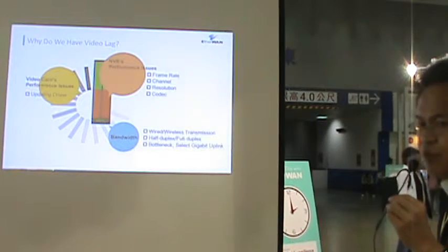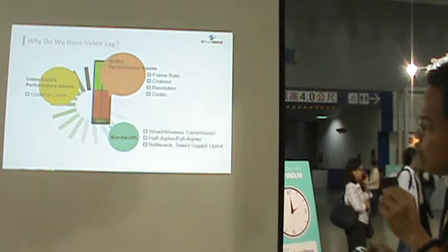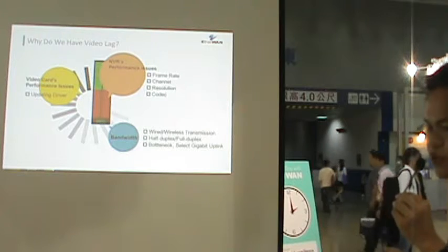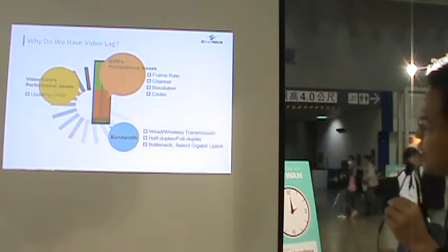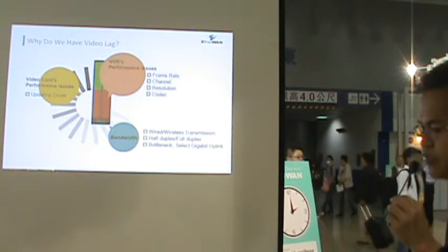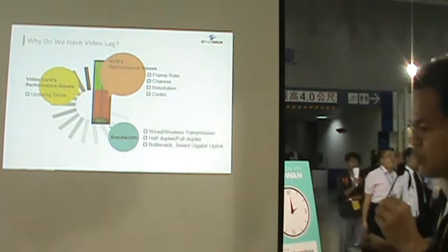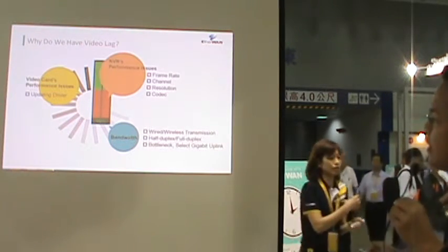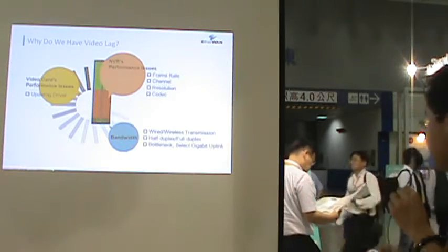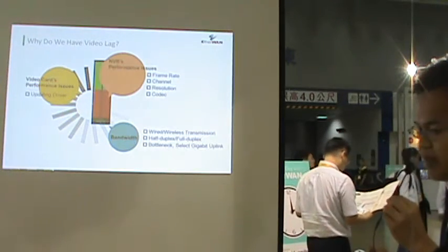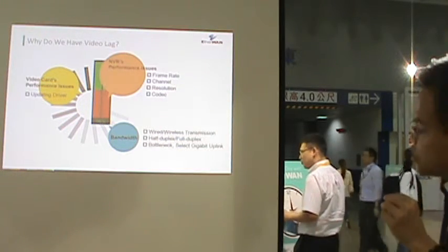Now, in this case, you will have propagation latency. When the frames arrive at the destination PC or NVR, they have a buffer to rearrange those frames, because those frames did not actually arrive in sequential order. So you have to rearrange them. This time is the decoding or buffering latency. So these are the three factors that we need to consider.